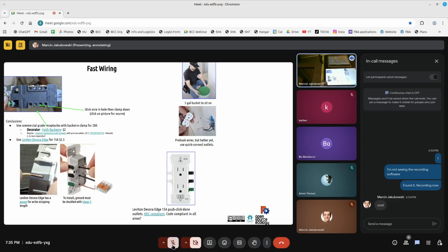The videos that dismiss SharkBite, there's a little bit of a learning curve there. Some people forget to chamfer the top, put it in, and use the depth gauge and things like that. But anytime you see somebody debunking SharkBites, they'll put it under like 10,000 psi and say, "Look, it busts at 10,000," where the maximum you'll ever see in a house is way far away from that.